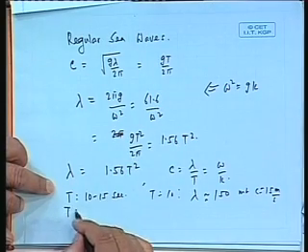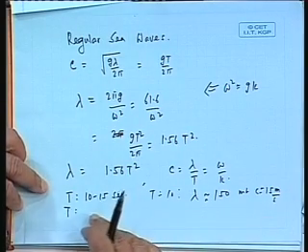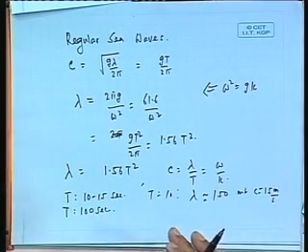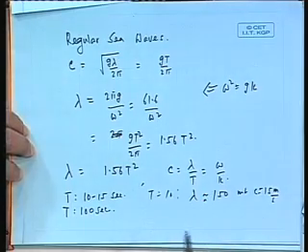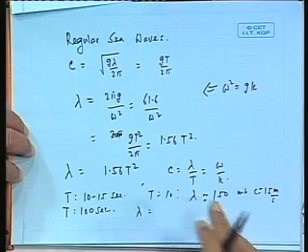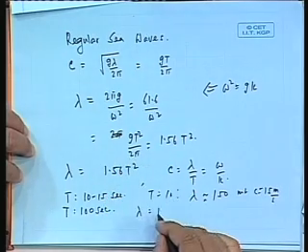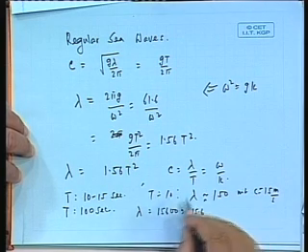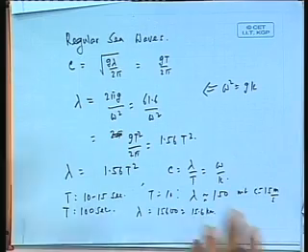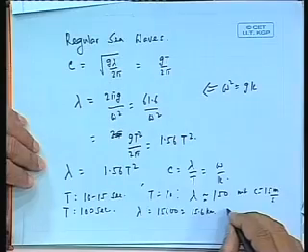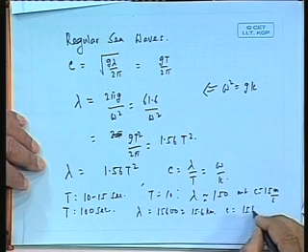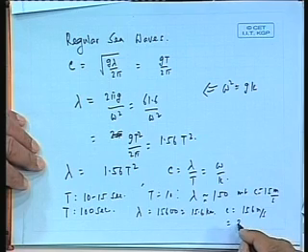Now, let me take for an example a very long wave and find the length. Let us say that T equal to 100 second, a very long wave, a 100-second wave. If T is 100 second, what will be lambda? Lambda is going to be 1.56 into 100 square, that is 15600 meter, or approximately 15.6 kilometer long, is it not? That can be a typical length of a wave called a tsunami, when a volcanic eruption goes. What is the speed of that? It is going to be 15600 divided by 100, which is 156 meter per second, about 300 knots.